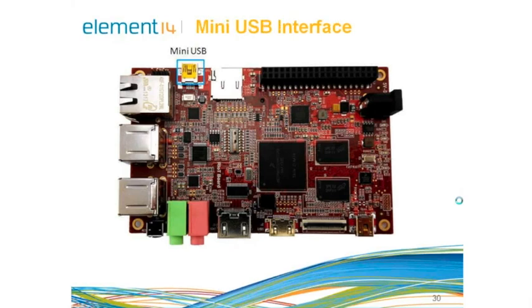It has a mini USB interface. The mini USB is connected to the high-speed USB 2.0 OTG module, that is on-the-go module, of the i.MX6 application processor, which can act as host as well as device for data transfer and communications.